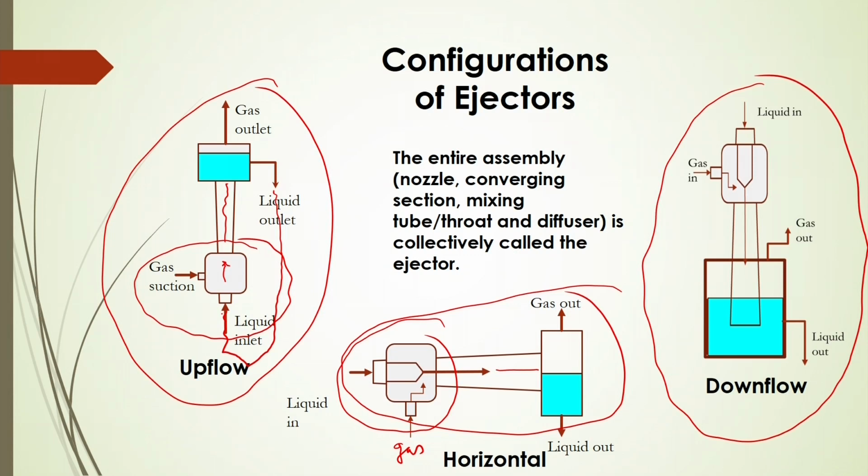Even if you are producing finer bubbles, they may go downward with the downward liquid momentum, but if the bubble size is such that the buoyancy force and downward momentum balance, those bubbles will reside in the column for a longer time.